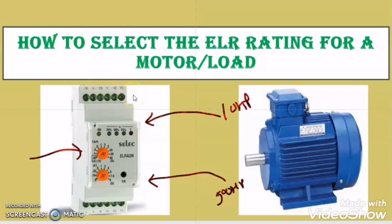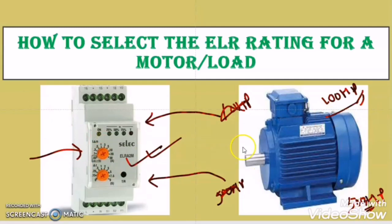I hope you understood this concept. I know it is very difficult to understand as it requires a lot of concepts, but I tried my level best to simplify this topic. Suppose someone asks you, if you have a motor of 100 HP, then what ELR do you need, and if you have a 500 HP motor, what ELR do you use, then you can say that the same ELR I can use for both ratings, as the ELR rating does not depend on the load current. You just have to take precaution about how much protection you need, how much earth leakage current you need to break. That range of ELR you have to select, and one higher range of CBCT you have to select.